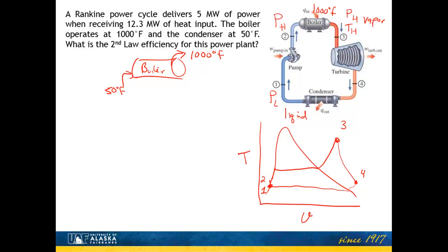Now let's consider, for example, a single pound of water. So the first pound of water comes in here. So we'll just have a little single pound of water, and that pound of water initially is at 50 degrees. And so the very first BTU of energy it absorbs, it's absorbing from a 1000 degree boiler, because the whole boiler is operating at 1000, yet the water is only at 50. So if we think about the entropy that's being generated, let's go back to this classic idea where I have 1000 degrees Fahrenheit, which is my high temperature source, and then I'm dumping heat into a 50 degree sink, which is my water, and I have 1 BTU of energy going in there. Now I've got energy leaving high temperature going into a low temperature.